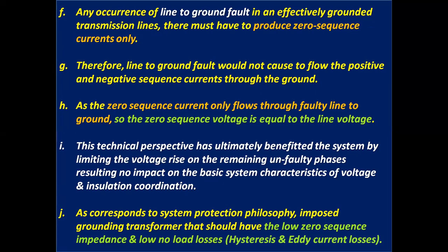As corresponds to system protection philosophy, the imposed grounding transformer should have low zero sequence impedance and low no load losses, that is hysteresis and eddy current losses.